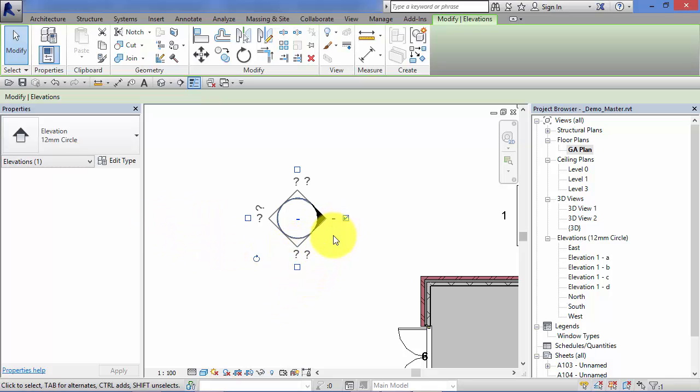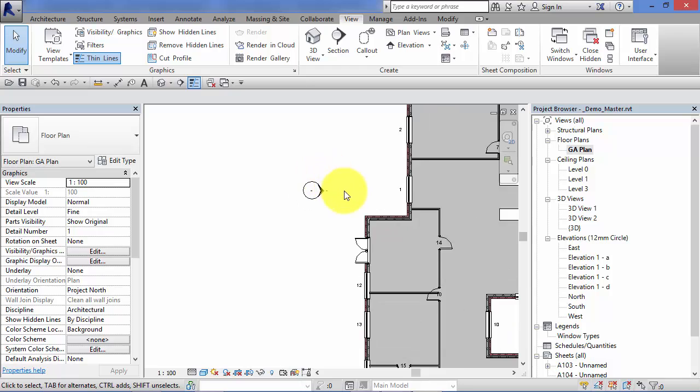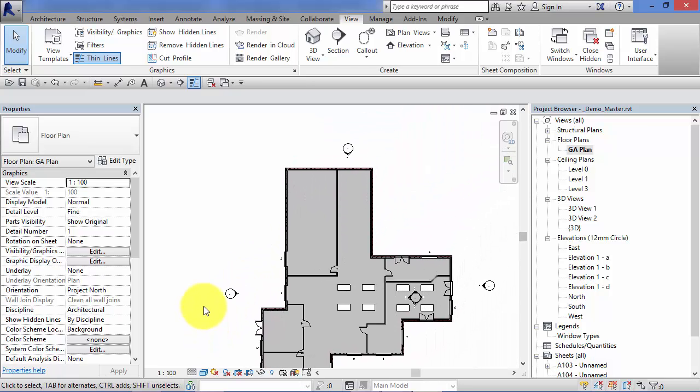It's up to you which elevation view you need generating. You can have one of them, 2, 3 or 4, and you simply put a tick against the elevation view that you want to be generated. So typically for external elevations, you'll just have a single elevation view being generated from a marker. So one here pointing at this side of the building. Then we need a separate elevation head here with one view turned on pointing this way.